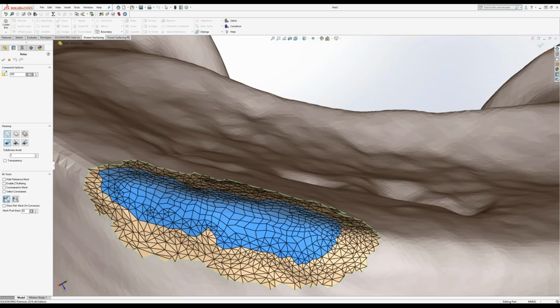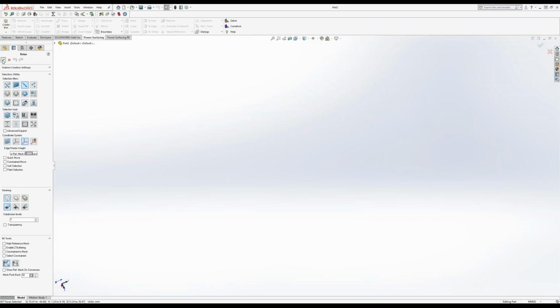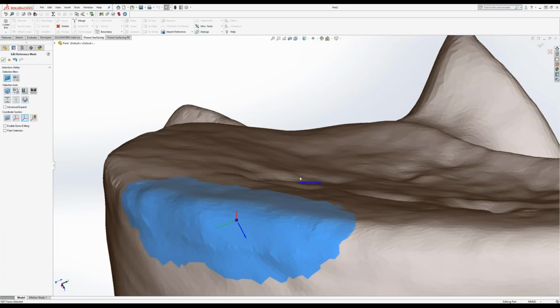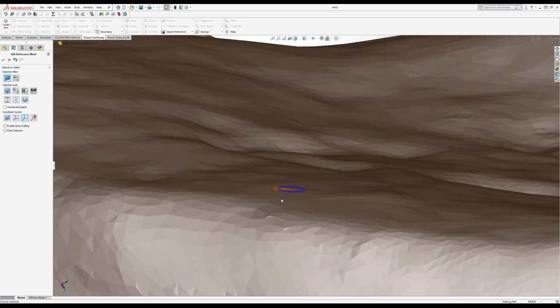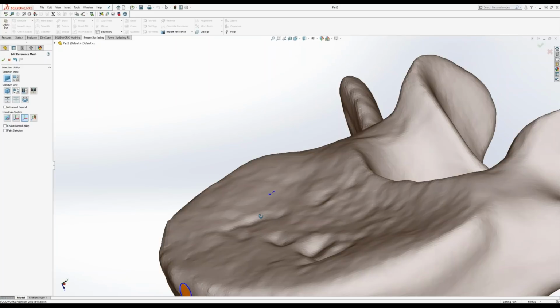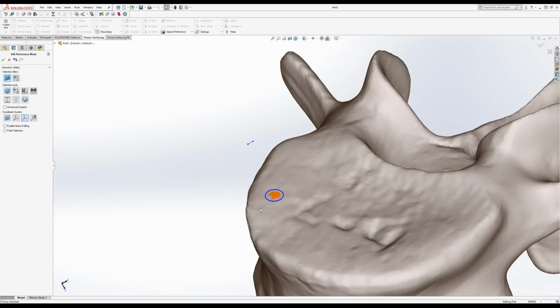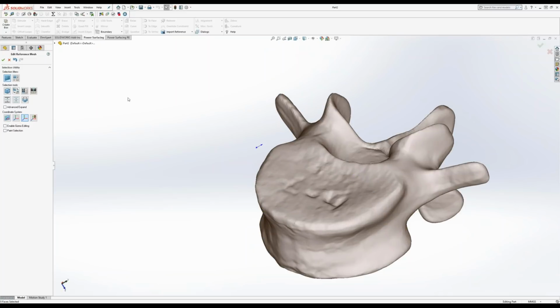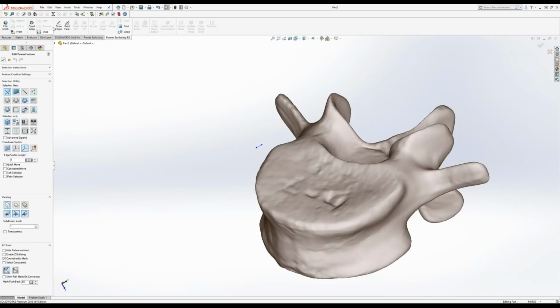And then when you're done editing, you can accept it, and it throws it right back into the original mesh. So now it's back inside this original mesh. And so when we retopologize, it will use the new geometry we have for that. So let me go through that process, and then I'll show you some other tools that we have. Okay, we're still in mesh editing. So let me get out of mesh editing, and so we're back in the level where we can do a quad wrap.